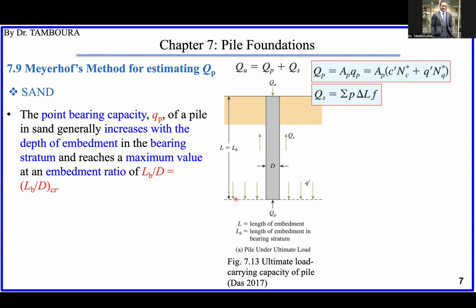What do we expect if the embedment of the pile increases? Normally, when the embedment increases, the effective stress also increases, because it is just the overburden pressure.